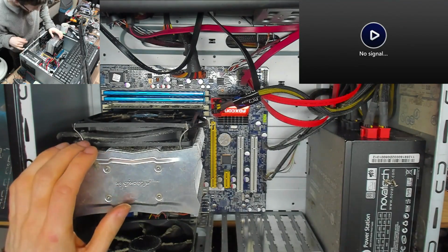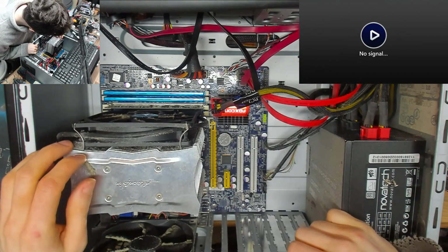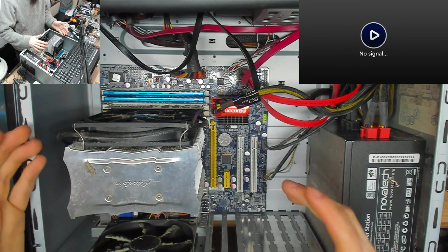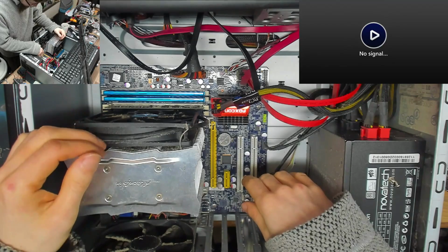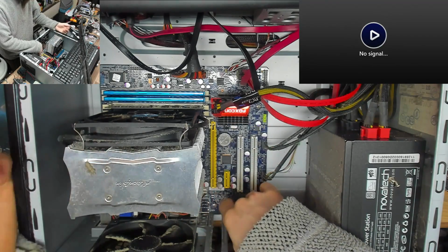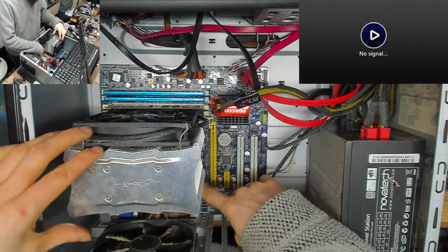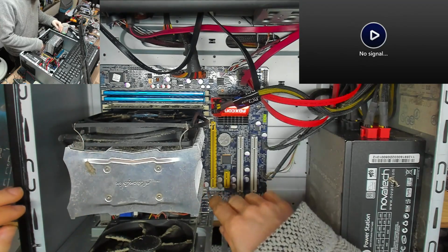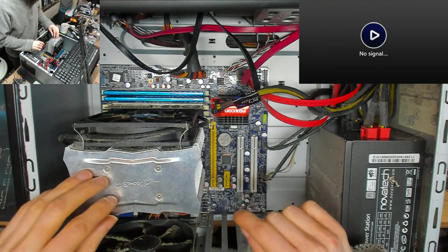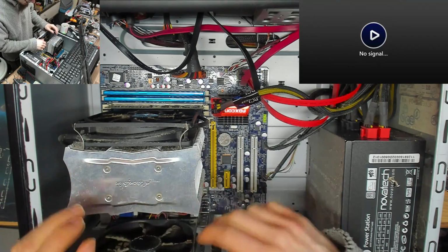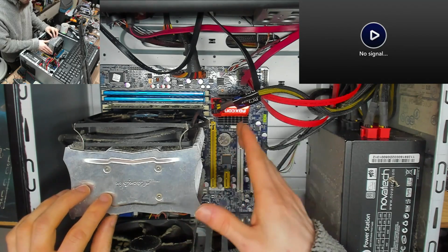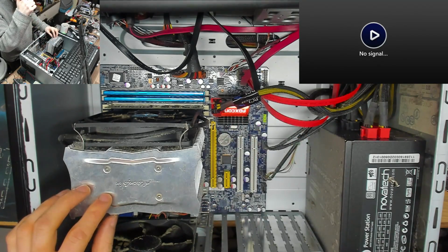Based on the motherboard, I'm guessing this is 2nd or 3rd gen Intel, just based on the general layout. It's a very naff motherboard, though. It's a cheap Foxconn job. There's no cooling on the CPU regs at all, and we've only got 4-pin power going in behind the cooler here. So it doesn't get a lot of power to the CPU either, which might be a problem if they've got like an i7 that they've dropped into this old motherboard or something like that.